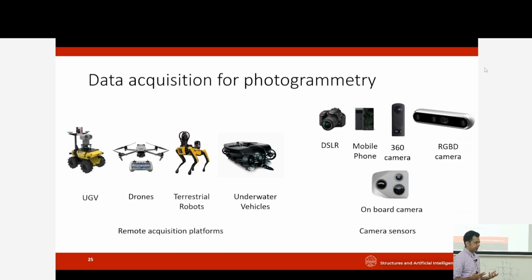Similar to a total station, where you have a laser, with LiDAR you have many, many beams that are cast, and then you get the reflections from all points, and that is much more accurate because it's measuring the time of flight of each of those rays. So you can get a much denser and richer set of points.